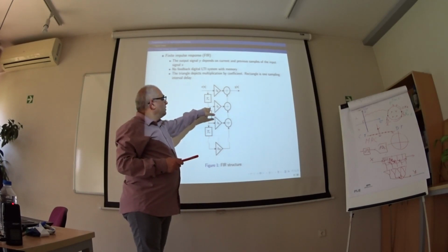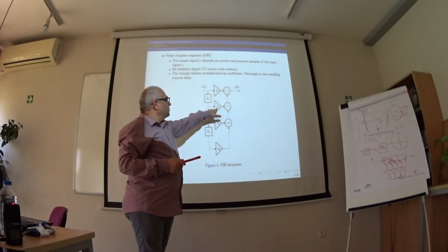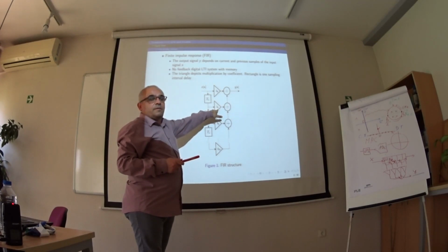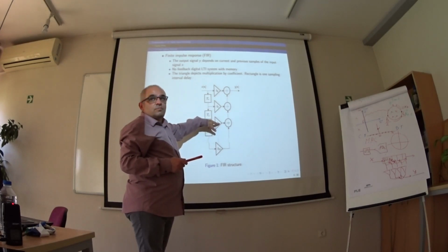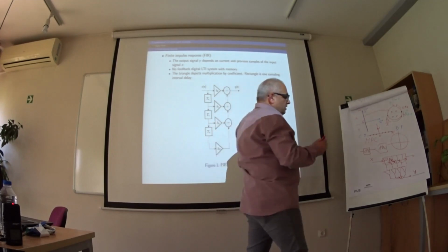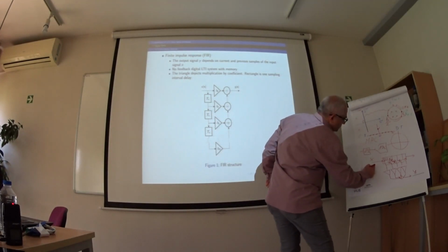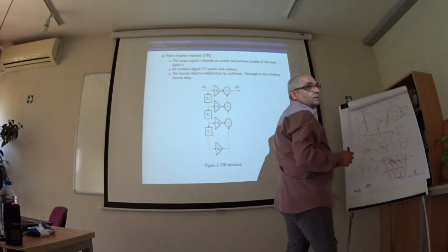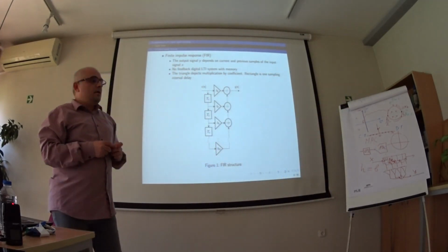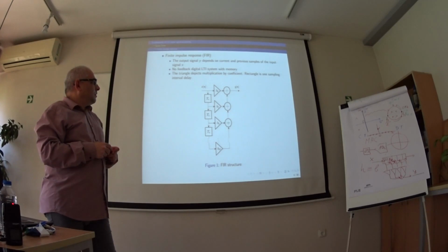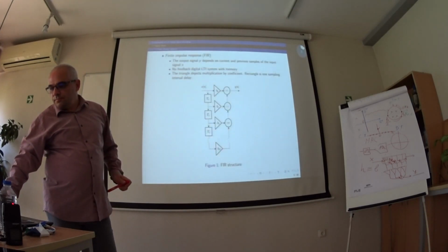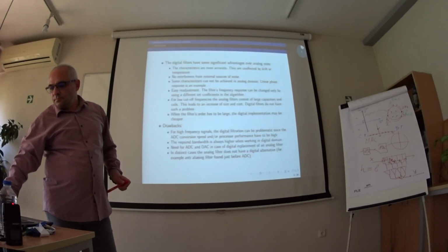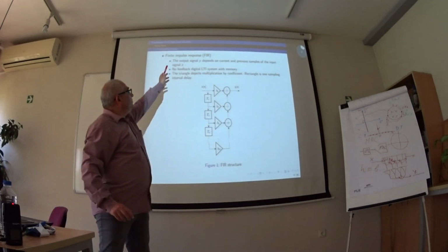And now at the output, we will see the coefficient B1. At the next sampling interval, we will see the next coefficient B2. So very obviously, the impulse response is the same as the filter's coefficients. So can we make coefficients to be infinite? No. So, finite impulse response.